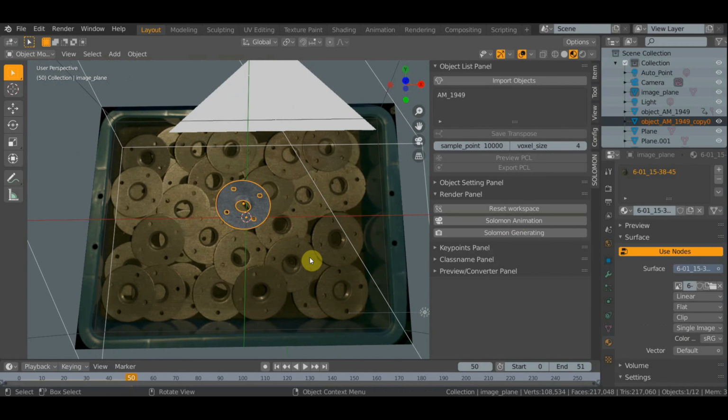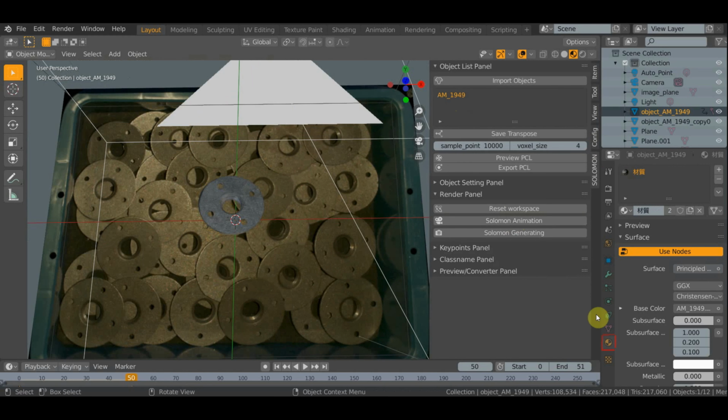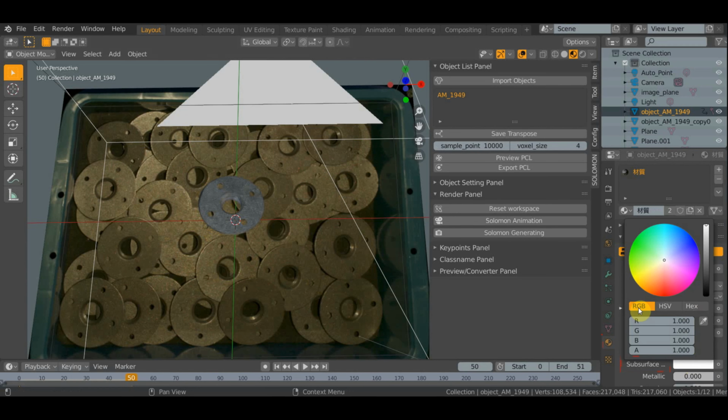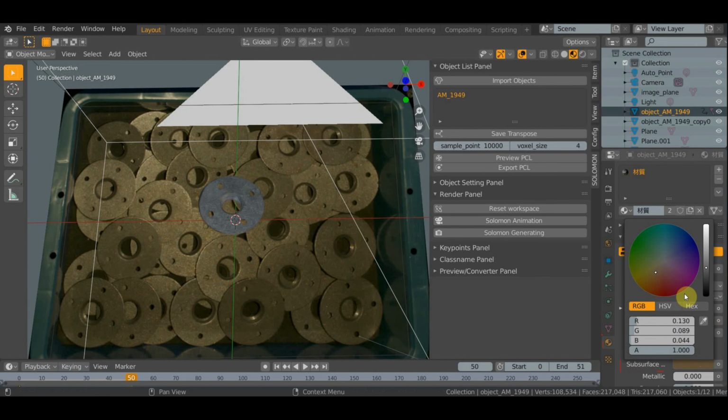My new objective is to imitate the real color of how the light from the projector is reflecting on the objects. To do it, I need to select the cat object in the Object List panel, and in the Material Properties tab, in the section Surface Color, select the option RGB and pick the eyedropper icon. This tool will help you copy the RGB color of the selected pixel. Therefore, I recommend copying the color of the pixel that represents the average color of the majority of the pixels of the objects. This color needs to be in the middle of the color clarity range. In other words, choose a color which is neither too dark nor too bright.